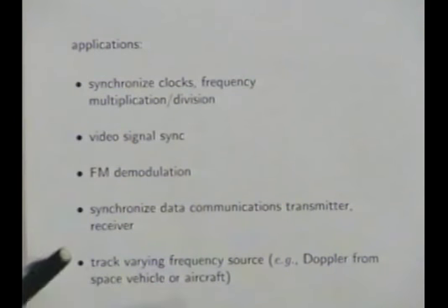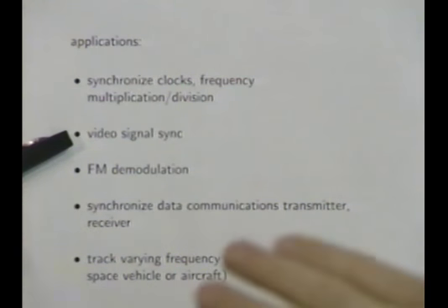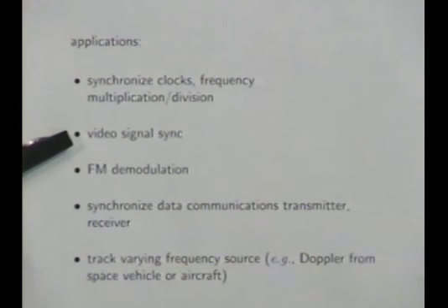And that's very useful. Another example is it's used to sync a monitor or a television signal. When you send out a video signal or an RGB signal to a monitor, if it says 72 hertz refresh rate, it's probably pretty close to 72. But it could probably vary from 71.8 all the way to 72.1. Probably that's too big a range. But the point is, whatever it is, if the two weren't synchronized, well, you know what happens: the whole thing slips, and you start seeing the bottom of one frame and the top of the other. That's because they've lost sync. And in fact, if they're off in frequency, what happens is it rolls, right? Because they both think it's 72 hertz, but one guy's actually sending you RGB signals at 71.99, and you can even work out how long it takes for the thing to roll. Okay, so a phase lock loop is what's used to synchronize these signals exactly.